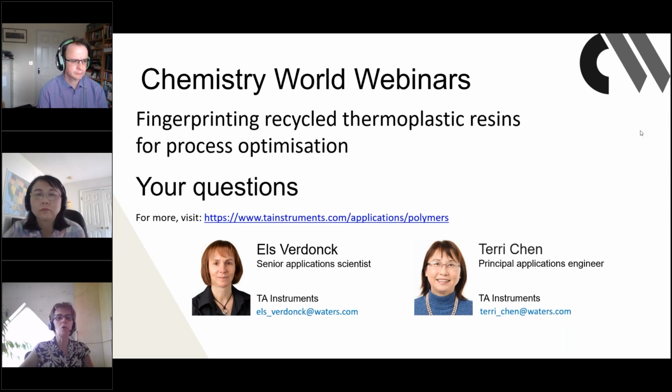At that moment, you might need a bit more, but for sure a couple of 100 micrograms should typically be good. And you can always play with the heating rate that you are going to use in the DSC. At the higher heating rates, you get more sensitivity. Or you can also play with the sample mass. And if the amount of contamination is very small, put a bit more sample in your DSC cup to also increase the sensitivity.